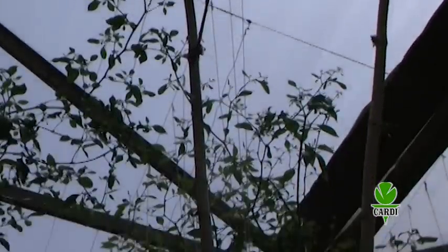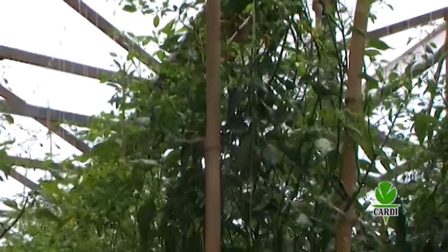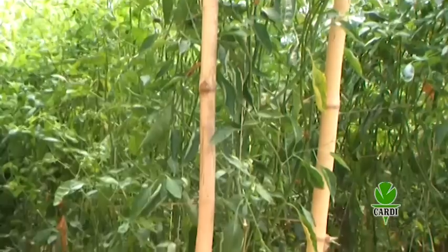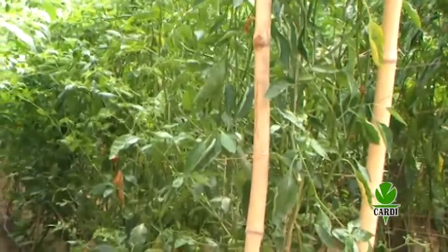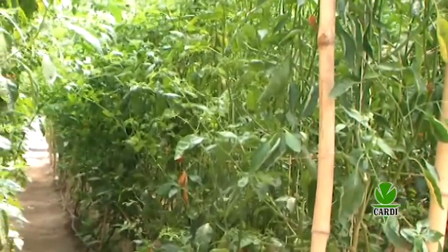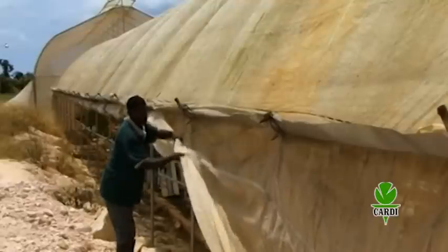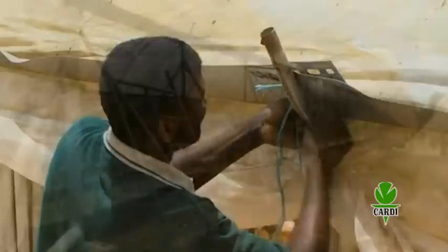In most areas of Trinidad and at sea level in the other islands of the Caribbean, the wind is not consistent or strong enough for adequate ventilation as stated before. As such, optimal conditions cannot be achieved using passive ventilation, despite use of the best designs. It may therefore be practical to use larger meshes or remove mesh sections in certain parts, for example, the roof vent in split-roof structures, or even have open sides.